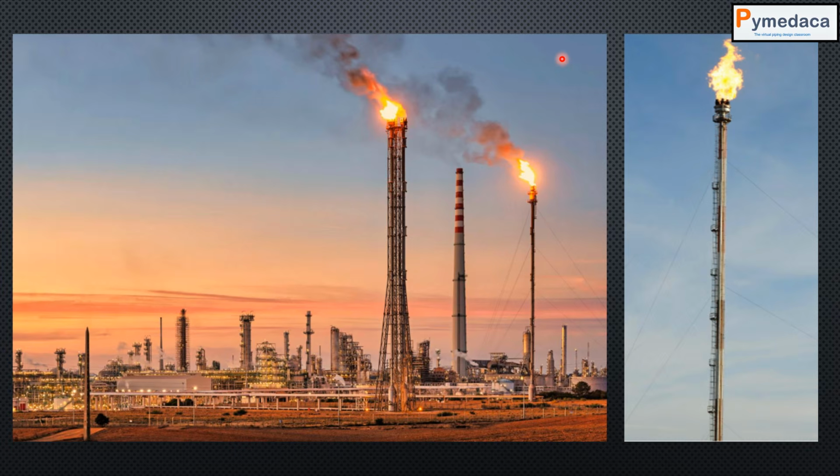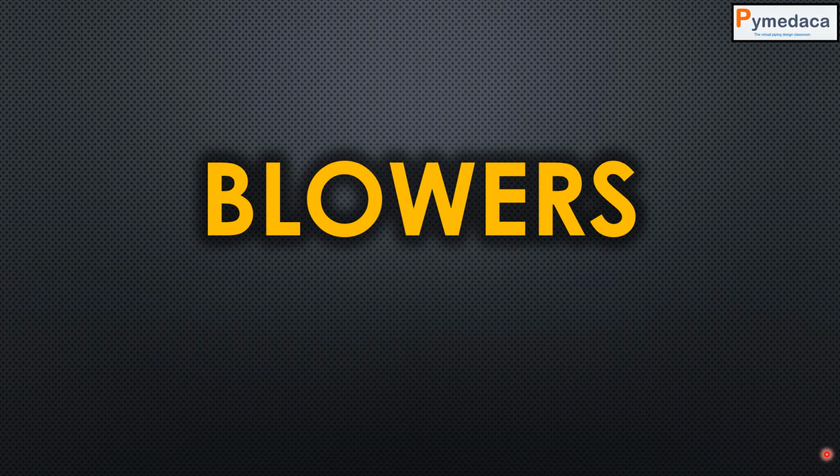So when you come to know about any flare package in your project, you should have a space for all of these things. You should fundamentally have a thought process about where to place a knockout drum, where to place a makeup drum, where to place a flare stack, and all these things actually. So that is how you should think actually. And the next one is blowers.